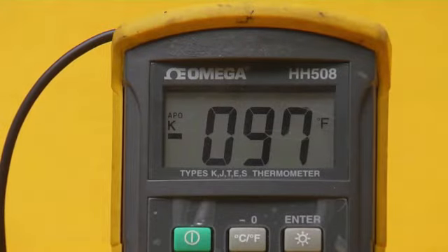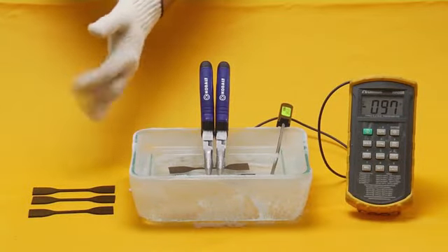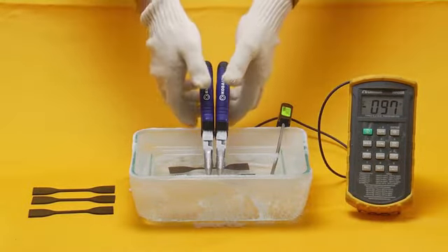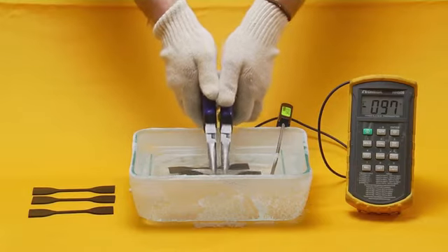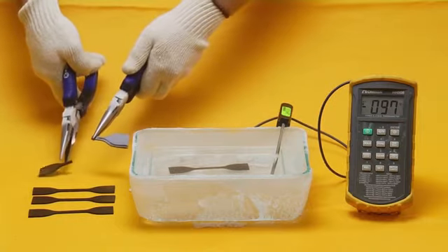Low temperature testing is imperative to ensuring sufficient seal performance in industries where low temperature operating conditions are common. Low temperature causes an increase in brittleness of the compound, which leads to cracking, breaking, and failure of the O-ring.